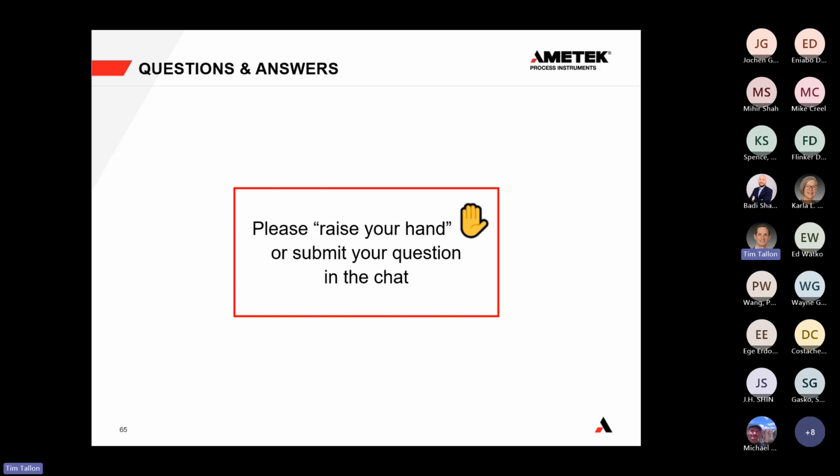And that's important because it reduces the potential for tramp air or ingress air from the outside to bias the oxygen measurement. So there's less risk for ingress air. There's also more opportunity to get a measurement that's reflective of the firebox in the process than downstream. So that's what they recommend.